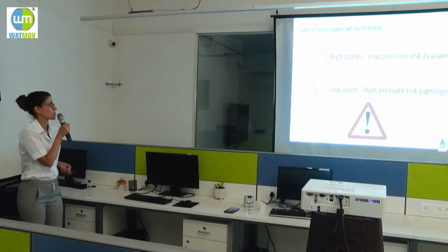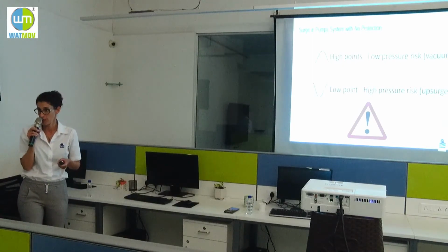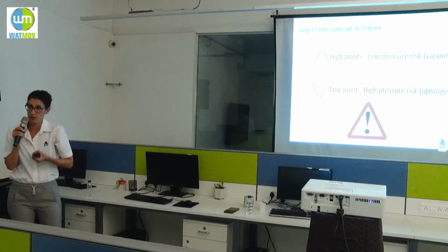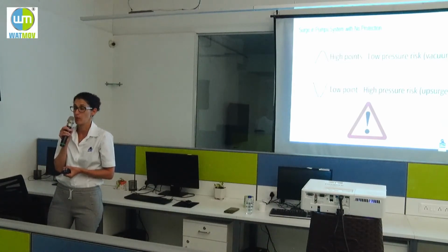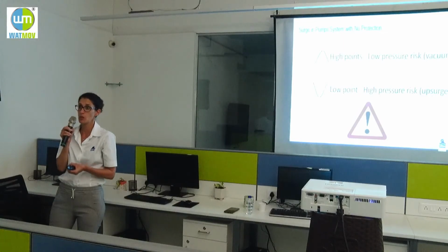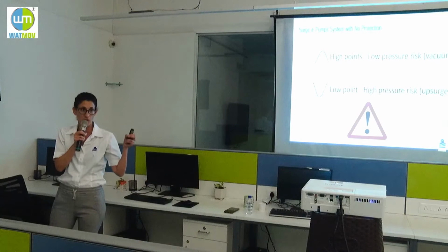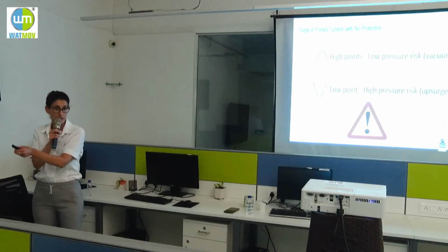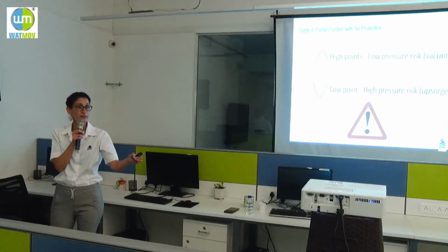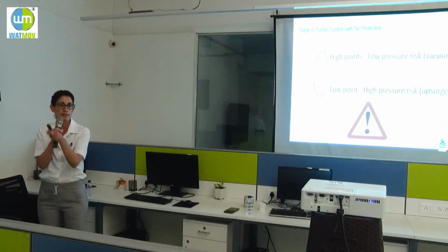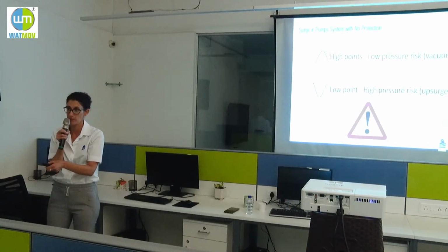So usually we will put an air valve on the high points, because the air valve will intake air in order to prevent vacuum conditions. Bermad's solution is a combination of a surge anticipating valve, which we will talk about, and an air valve. The surge anticipating valve dissipates the positive wave, and the air valves treat the negative wave, preventing vacuum conditions and pipe collapse.